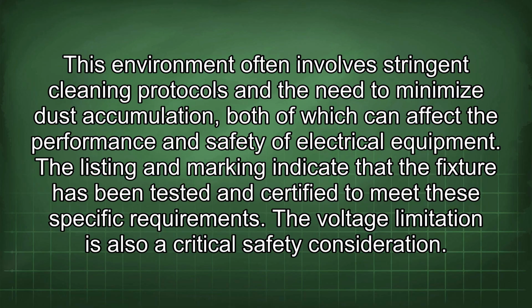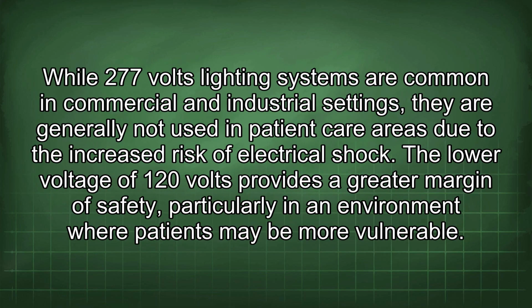The voltage limitation is also a critical safety consideration. While 277 volt lighting systems are common in commercial and industrial settings, they are generally not used in patient care areas due to the increased risk of electrical shock. The lower voltage of 120 volts provides a greater margin of safety, particularly in an environment where patients may be